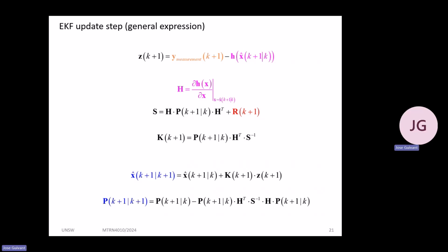Where do we tell this Kalman filter update about the quality of this, or the covariance, more exactly, of the noise affecting this measurement? Well, it's in the R matrix. We need to provide that. Usually we do know, because we know how wrong our sensor could be when it's measuring. Good. What are the participations? Here we have this H. What is this? It is the output equation. Our output equation is H of X.